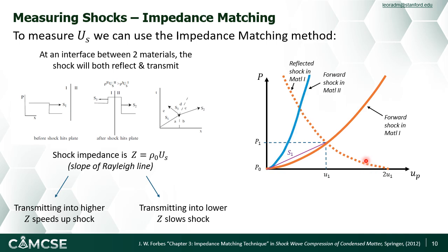And we can then plot out our material 2. In this case, we have a metal with a steeper curve, showing us the stiffer material. This gives us the ability to understand not just the state that we start at when we're reflecting, but also the state that we could go to based on the impedances in the new material.